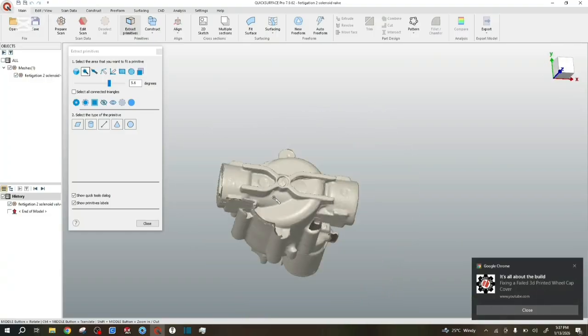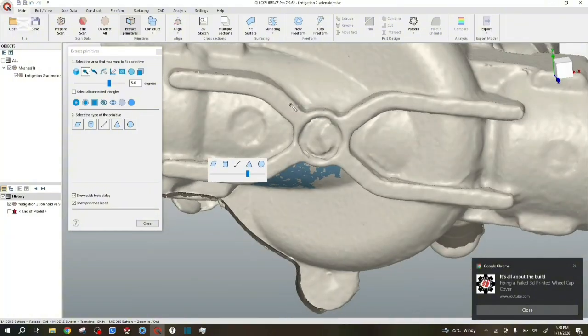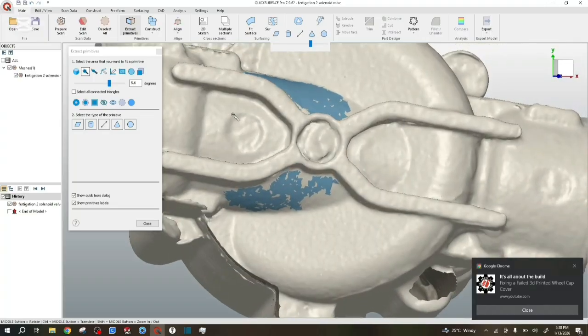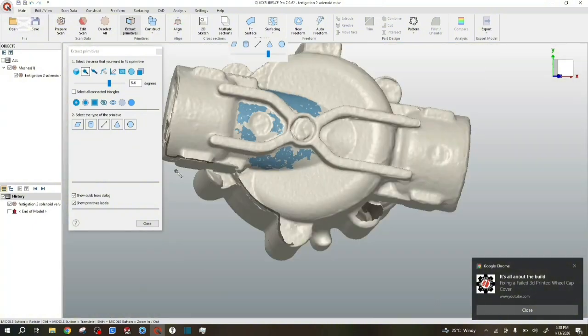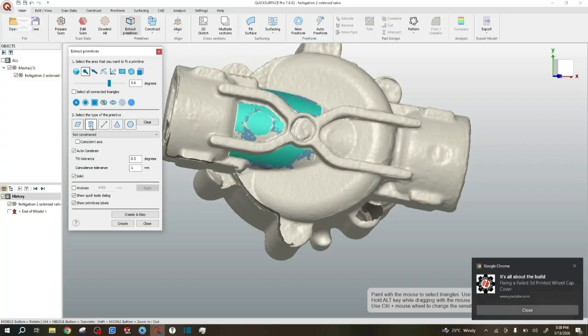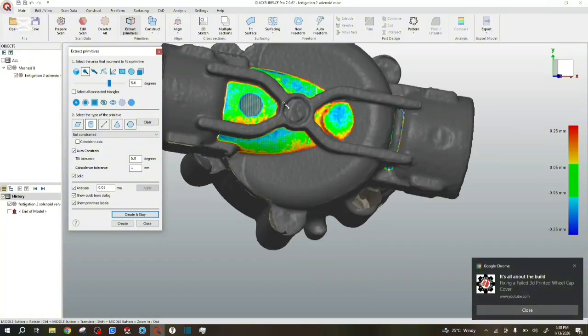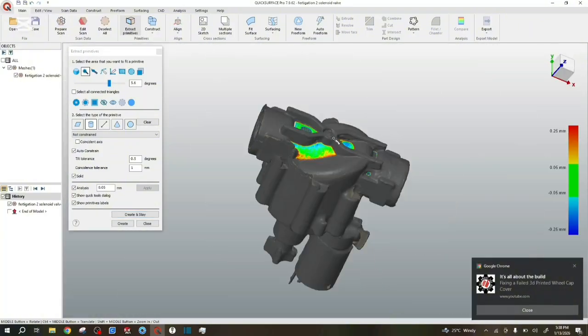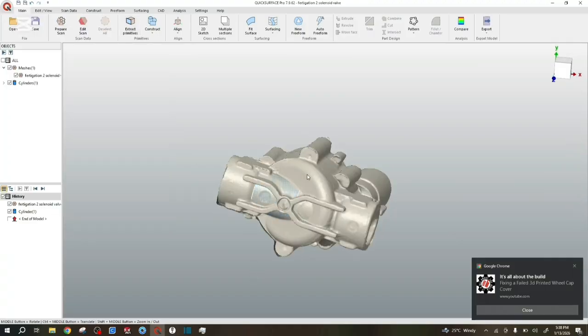The first feature that I identified was a cylinder. So we're going to choose the magic wand and then click on it. Cover as much area as we can. Cylinder, and then I can see that side, this part, and this other part. Like so. Once we have that area covered, click on the cylinder and check the analysis tool, and we can see it's mostly green. I think this is good enough, even with the noise of the mesh and everything. So we click on create. This would be our first feature that we'll use for alignment.